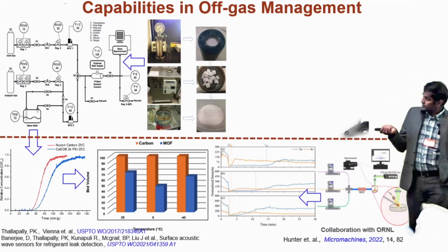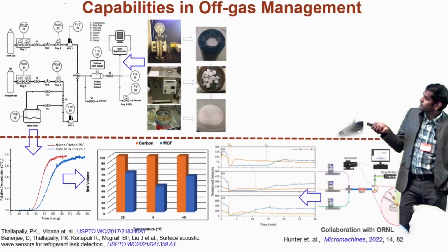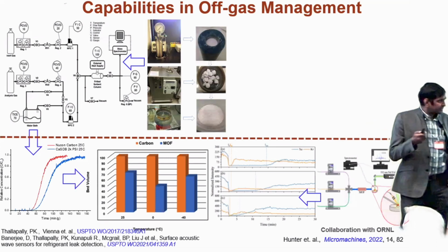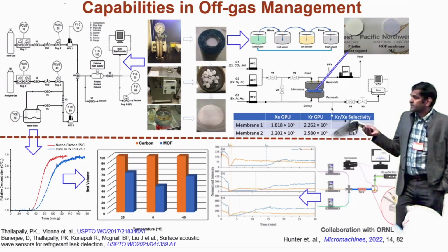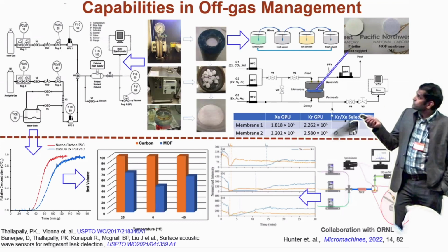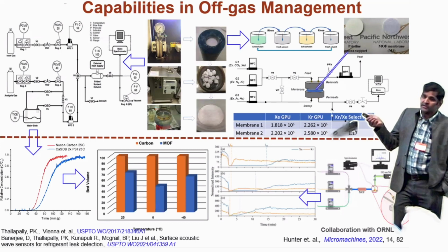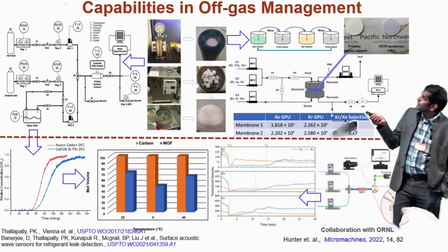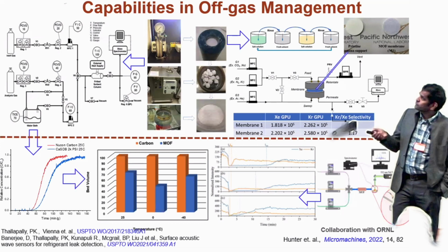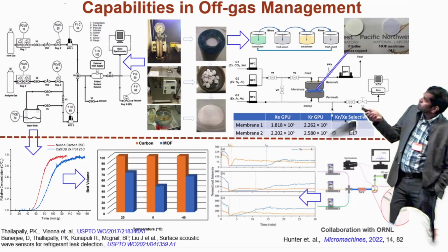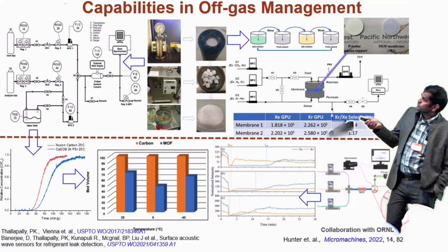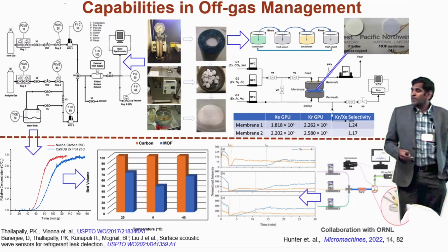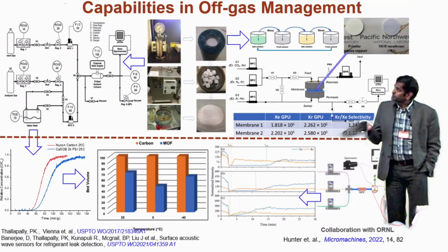Apart from these engineered particles, we are also collaborating with ExoDis on the same class of material, but we are trying to use the MOFs as membranes as opposed to engineered beads. Here is just an alumina support. We grow a thin film of MOF on top of this material by a layer approach, and we put these membrane discs in between these two discs here, pass the xenon krypton gas mixture, and measure what's coming out from the other side of the membrane.